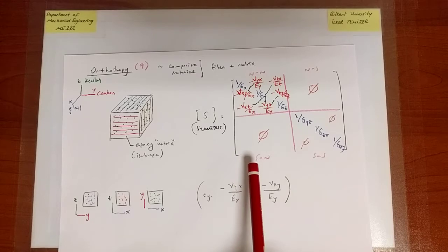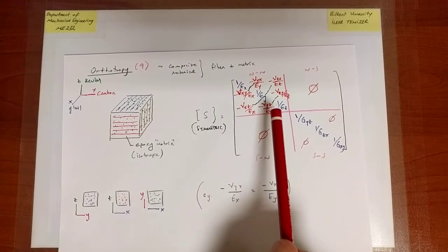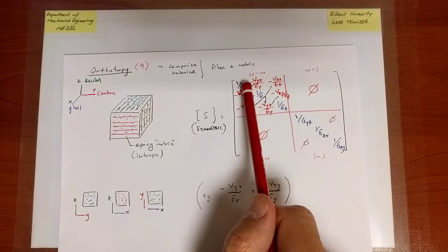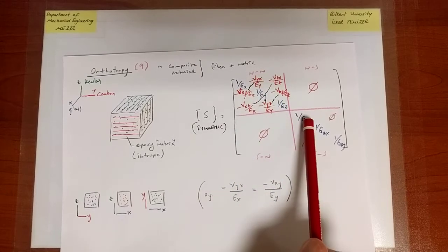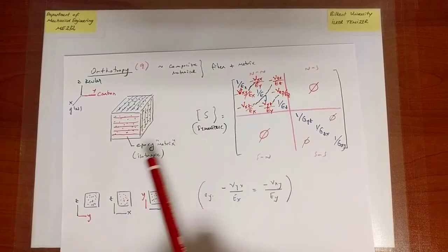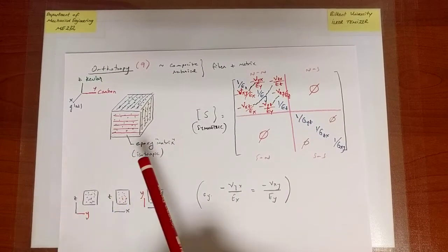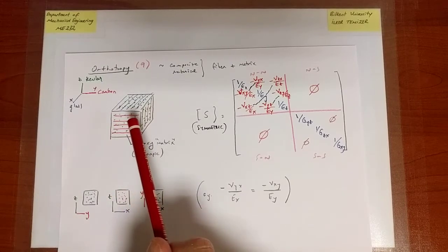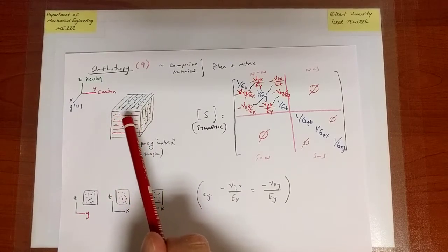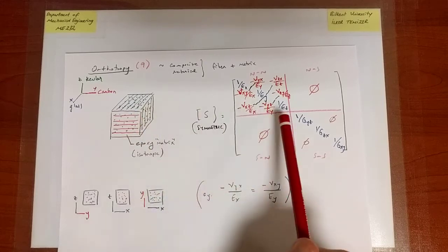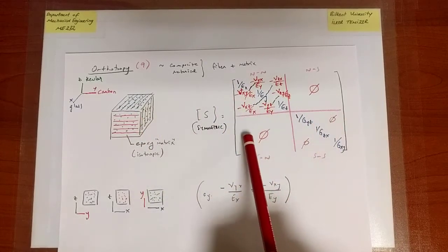So the only thing it can be is cubic, right? So in other words, E and nu are independent parameters, but so is G. It's not related to E and nu through the usual relation. So therefore, the exact choice of fibers that you put in influences the outcome of this structure significantly.